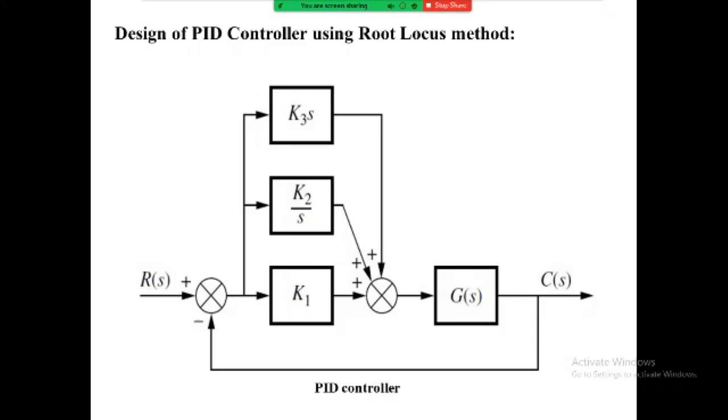This combination of PD controller and PI controller gives us the PID controller, implemented using active components, for example, the op-amp as an active network. What exactly is a PD controller? It is the sum of a differentiator and a pure gain, also called an ideal derivative compensator. Its purpose is to improve the transient response of the system.